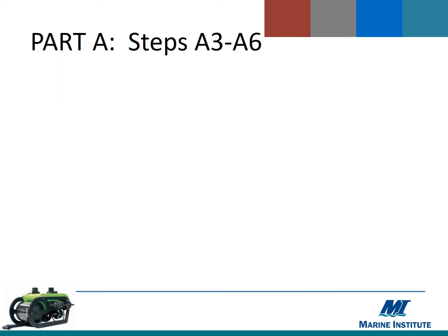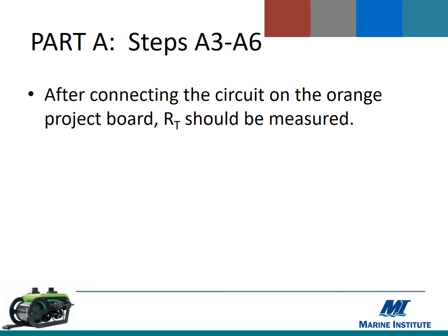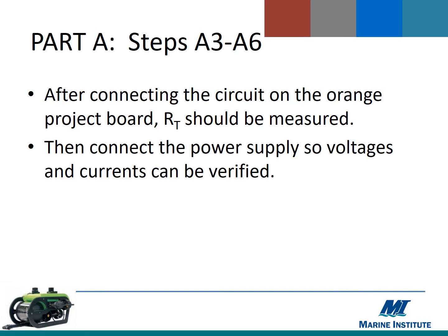Now, the next step is to build the circuit on the orange project board in the lab. Before you connect the power supply, you want to measure RT using the ohm meter. After that, connect the power supply, and then you need to measure the voltage across each resistor and the current through each resistor. Record the values in table 6.2, and those values should verify your calculated values from table 6.1.